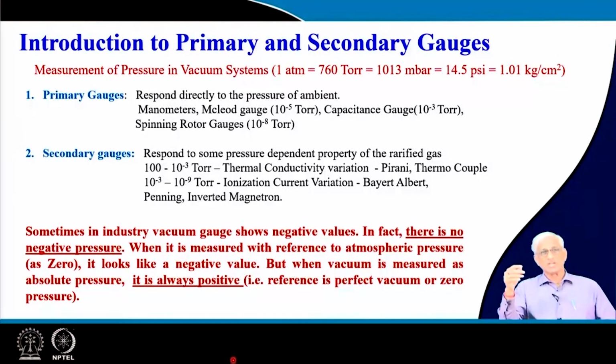That means we are measuring vacuum not in the direct sense using fundamental principles, but using some related parameters which are user friendly, may not be that accurate. They are secondary gauges. We need to calibrate them using primary gauges now and then, and recalibrate the moment you doubt that something is getting spoiled, or it is not measuring correctly.